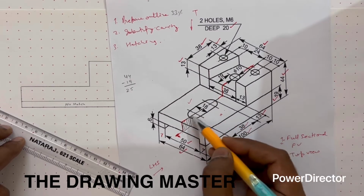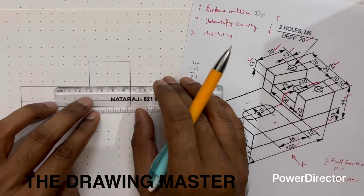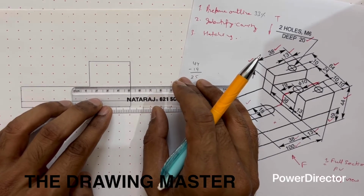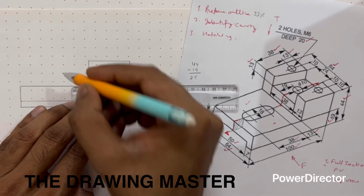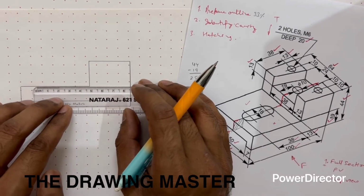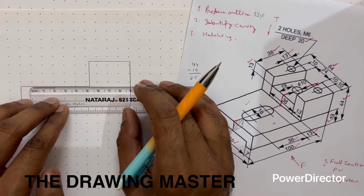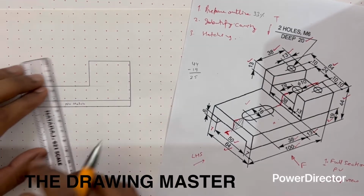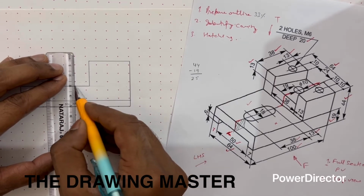At this cutting plane there is a cavity of 38 mm and there is a 13 mm margin from this point. So from here we'll take a margin of 13 mm. You can measure 13. This is 10, 11, 12, 13. After 13 mm there is a cavity of 38 mm. This is 35, 36, 37 and 38. So this is the cavity in the plate.